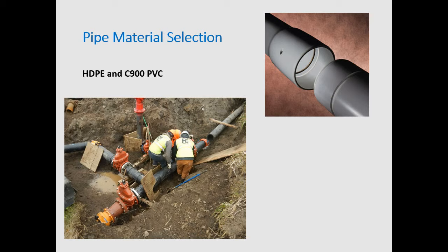They were hesitant to use PVC. Stigma is probably not the right word, but the concern is that it's a more fracturable pipe, it's brittle. Even though C900 is not, it was still a concern for them, as well as the fact that they're putting in HDPE. They wanted uniform pipe materials, but you just really can't use the HDPE in petroleum soil.